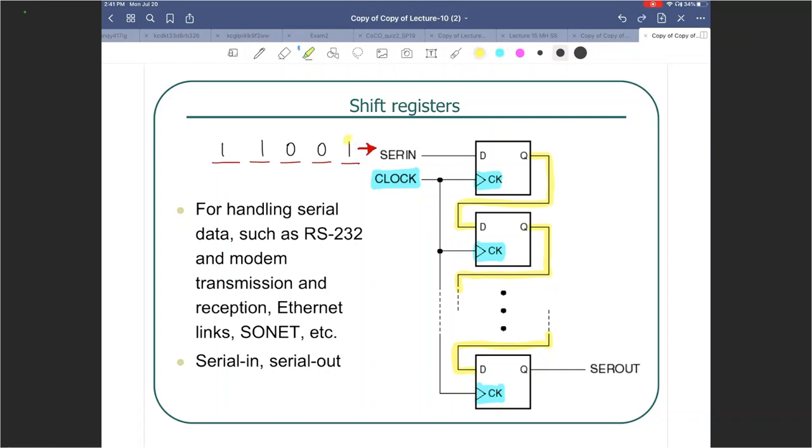As 1 goes in, the output of the top flip-flop is going to be 1 here. And all the others, I don't know. They are random right now. Maybe I cleared everything to 0, so they might be all zeros at the beginning. But I only know for sure that after the first positive edge, over there I have a 1.